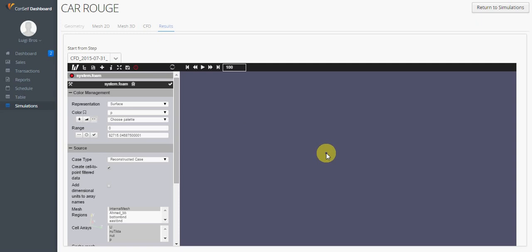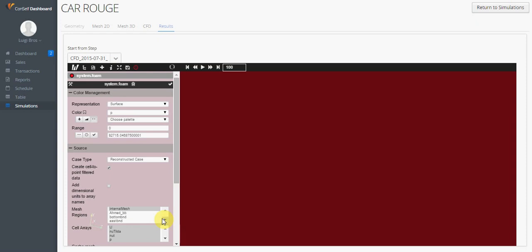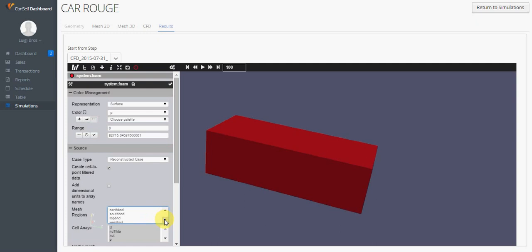When a simulation is done, we get the data not just for the fluid, but also for all the boundaries we defined during previous steps. As you can see here, there is a list of all these boundaries. Internal mesh is the flow, the internal fluid zone. But I also have Ahmed, which is the car I inserted, and bottom, east, south, top, and west, which represent all the bounding box areas. I select the Ahmed and I press apply.